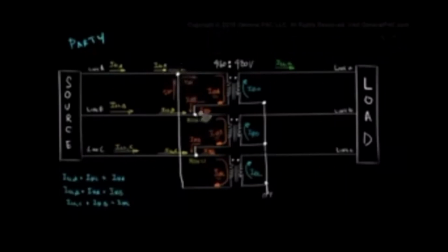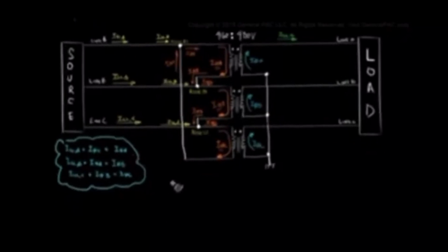So let us illustrate, in part 5, the nodal analysis on node A1, node B1 and node C1, and the relationship between line current and phase current. These are the equations that we come up with. Line current A plus phase current C is equal to phase current A. Right now we're going to evaluate this particular equation from a phasor diagram perspective, to turn this equation into something that makes a little more sense.